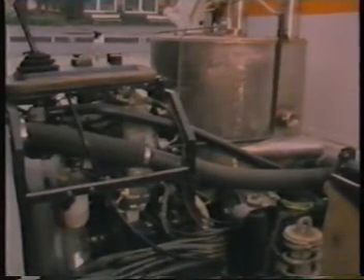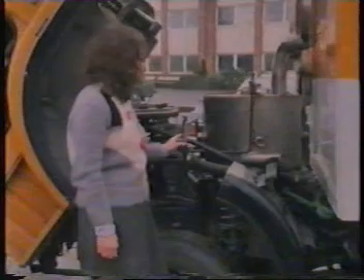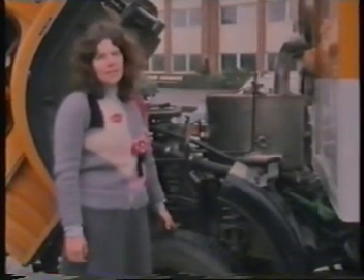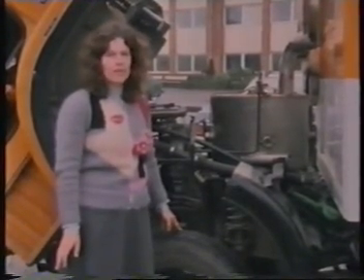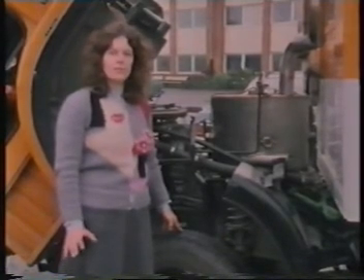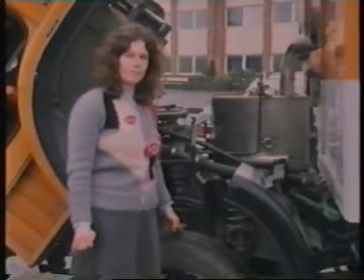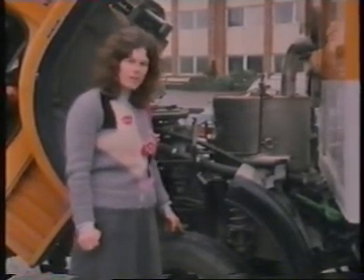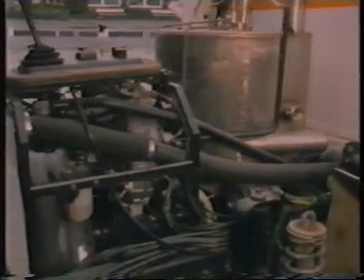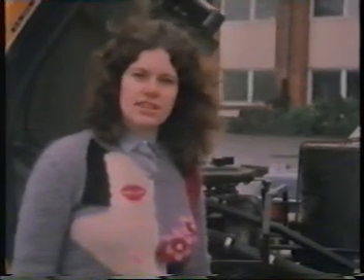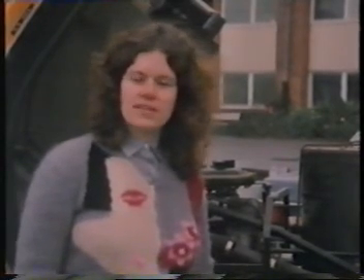The most obvious feature of a Stirling engine is this huge combustion chamber. The working parts are mounted underneath. You remember from the studio model that in a Stirling engine, the working fluid is entirely separate from the hot and the cold reservoirs. The working fluid goes through the Stirling cycle, following the route that you're familiar with from the PV diagram. The hot reservoir is provided by the combustion chamber, and the cold reservoir is provided by cooling water underneath there somewhere. The important thing is that it's just the control mass in the cylinder that undergoes these pressure and volume changes. The control mass stays there.